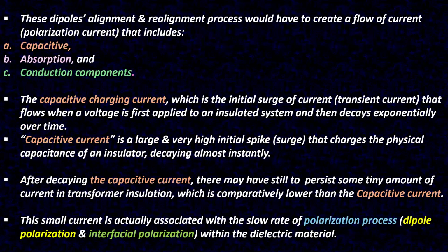This dipole alignment and realignment process creates a flow of current, that is polarization current, that includes three components: capacitive, absorption, and conduction components.